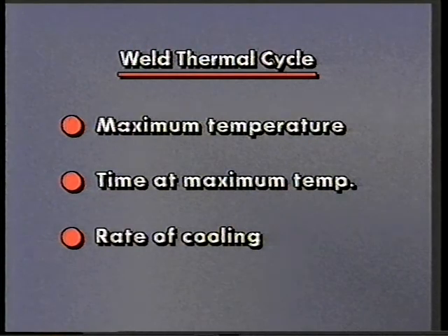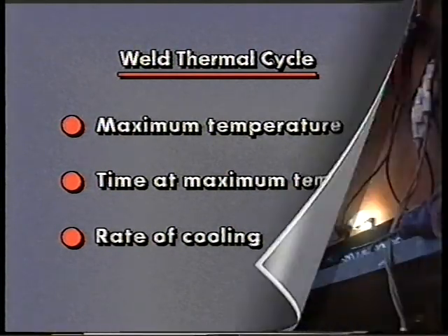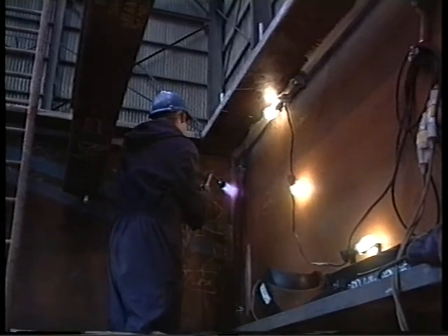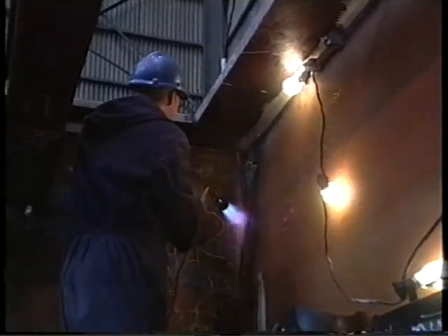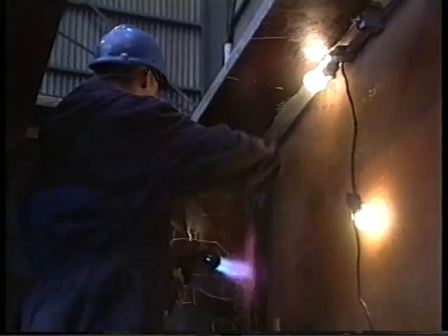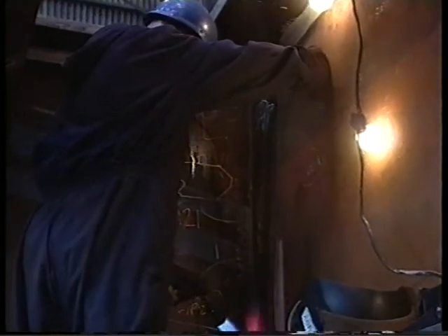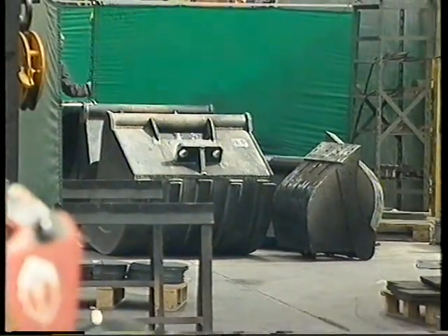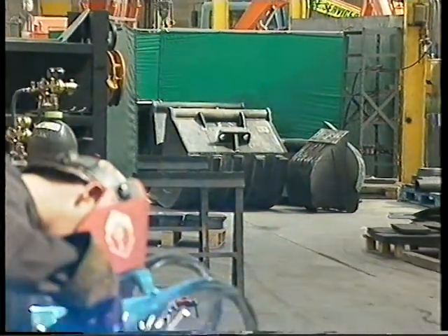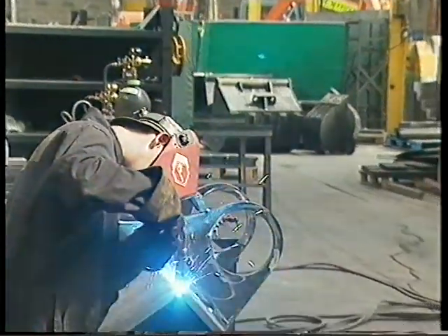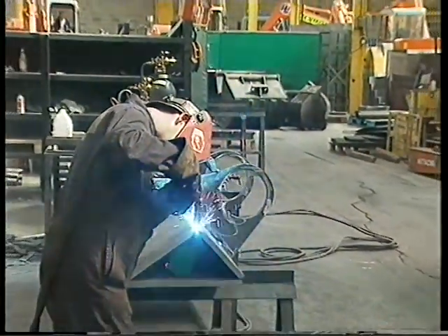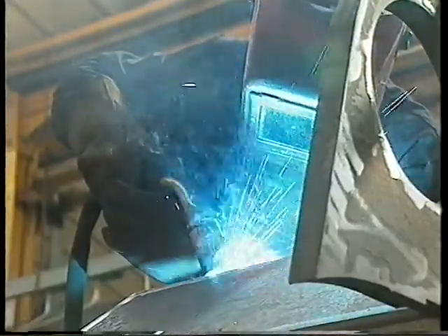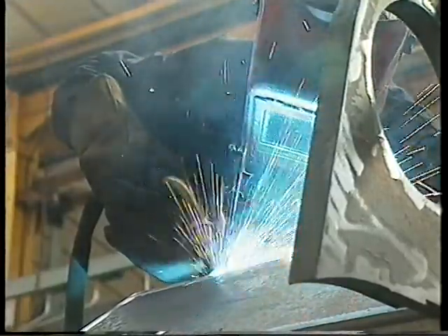For thick sections over 25 millimeters, it might be necessary to preheat the joint area to around 100 degrees centigrade, and it's often necessary to heat treat the whole joint afterwards in order to obtain the optimum mechanical properties. Mild steels can all be welded by any of the commonly used welding processes, but gas metal arc welding allows good welds to be made whether the operator is welding thick sections in industry or an enthusiast repairing a car.